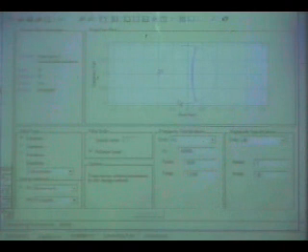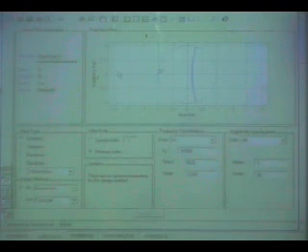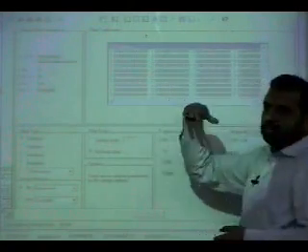Okay, then you can take these if you want second order sections, or you want them in B's and A's. Usually we prefer second order sections. Second order section means that this is your second order difference equation. There will be 15 of the second order, and 1 will be a single order, because total order is 31.